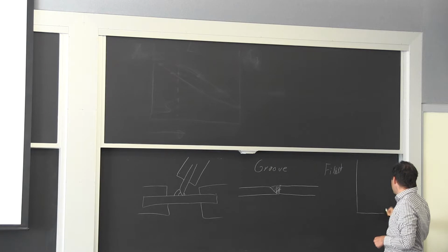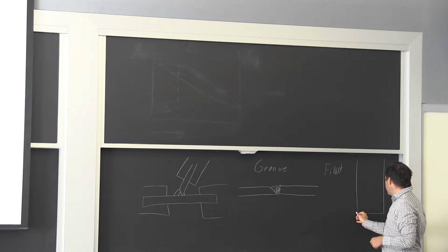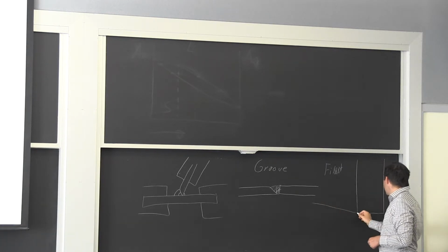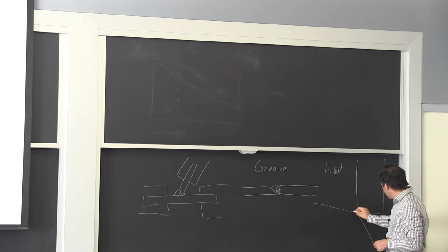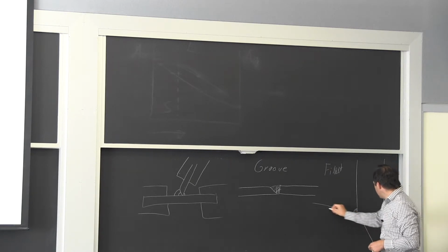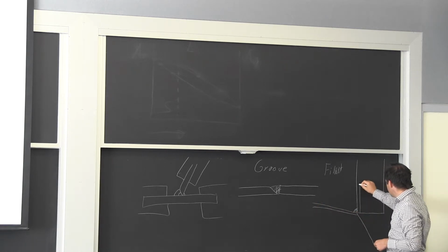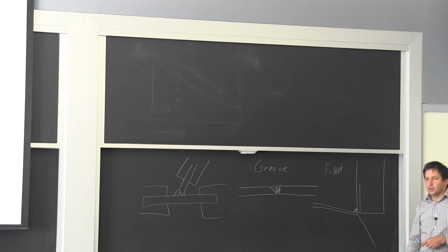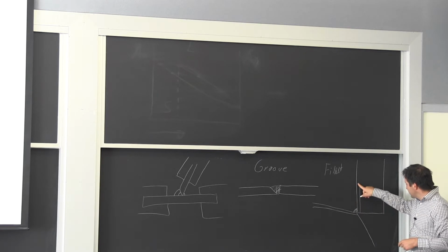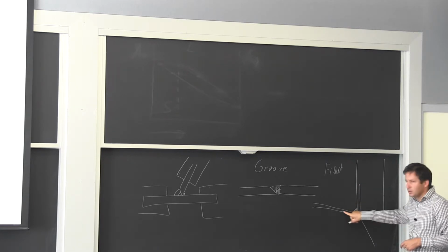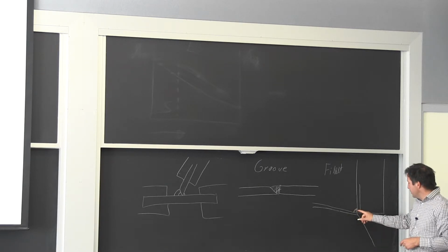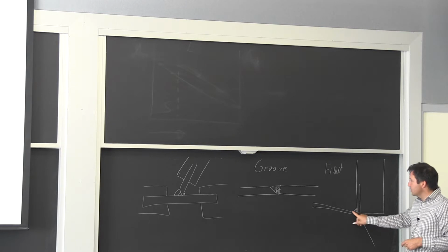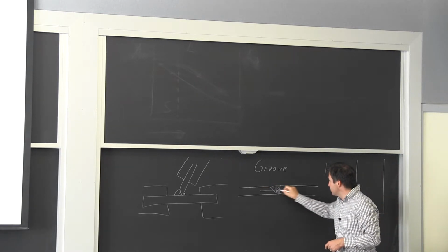So say that's the tube, and it's welded to another tube here. So I'm putting a fillet weld here. Out of this geometry, I have a lot of stress concentration. Stress goes from one tube through the weld to the other one. It's very much higher local stresses than if I'm just going through my member like this.